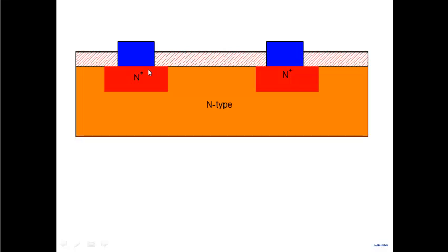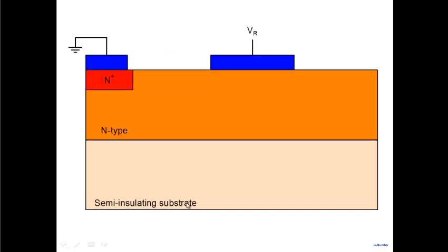You make the barrier very narrow, and the electrons are able to tunnel back and forth, and thereby provide small contact resistivity. Note two things happen by doping it very high. One is that rho c becomes very small because of tunneling, and also the sheet resistance under the contact becomes very low. So overall contact resistance then becomes very small through this means here.